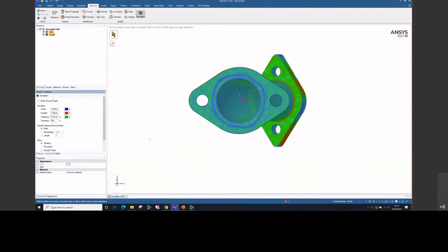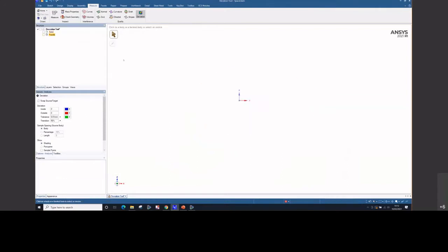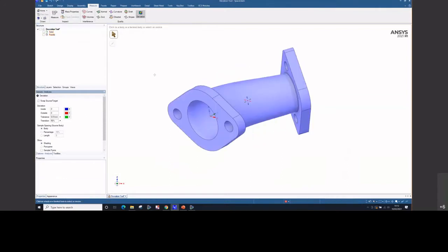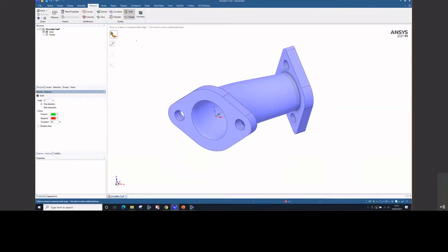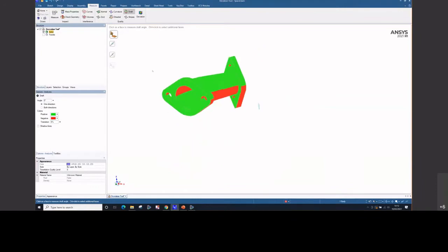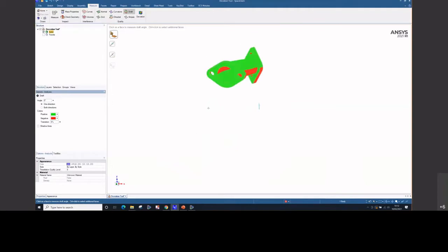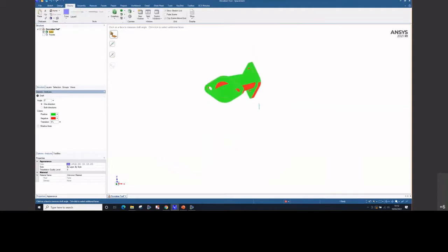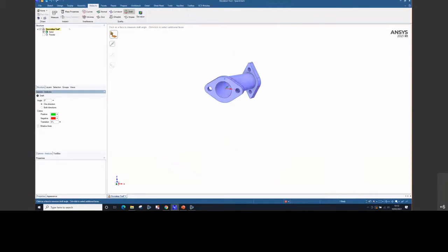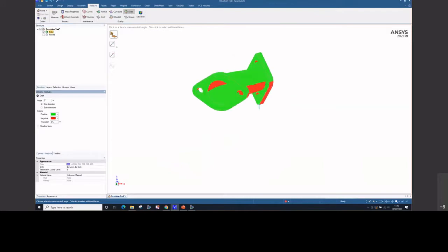Let's have a look. I could show you on this model, but I'm going to open up a new one. If we use our draft tool on this part, I might choose a pull direction if I can find my Z. Global world origin, it is. Oh, that's right in front of me. So using the draft tool, you can click on our parts, and I can change my pull direction to the Z, which already is.